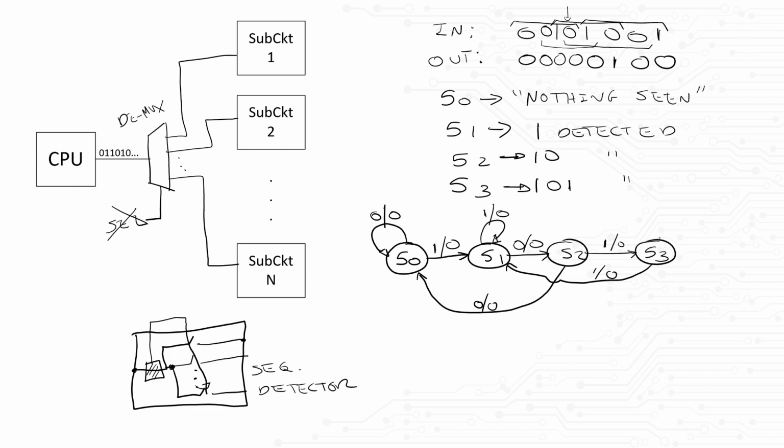Again, being an overlapping FSM, we can check what state closely resembles the new sequence 0, 1, 0. In this case, the last 2 bits, 1, 0, correspond to state S2, meaning we're again in the middle of a new sequence. And our FSM is completed.